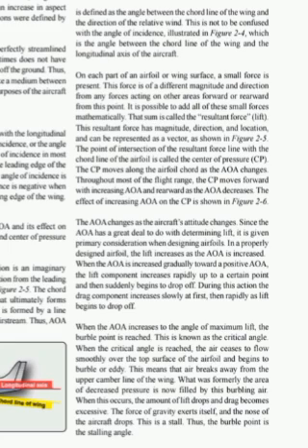This means that air breaks away from the upper camber line of the wing. What was formerly the area of decreased pressure is now filled by this burbling air. When this occurs, the amount of lift drops and drag becomes excessive. The force of gravity exerts itself, and the nose of the aircraft drops. This is a stall. Thus, the burble point is the stalling angle.